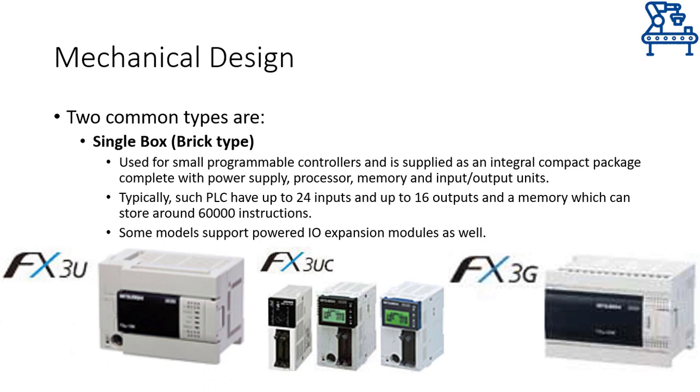These PLCs are ready-to-use PLCs and hence are preferred for small processes that require quick automation solutions. Although the idea of a brick PLC is to provide a fully packaged PLC, some manufacturers do provide brick PLCs with support of powered I/O expansion modules. Hence, if the need arises, a limited expansion can be done to these PLCs.